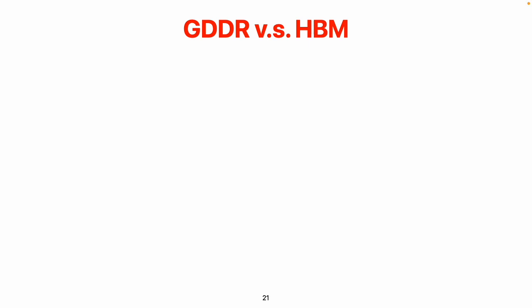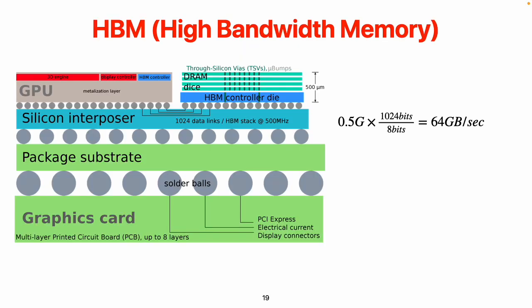All right, so here's the thing. A lot of people might think, even though I have a lot of money, why don't I just make it wider or stack as many layers as possible? The answer is that you can't, because there's going to be a thermal issue. If you have more stacks and put everything within a small tiny area, that makes the heat dissipation a lot more difficult.